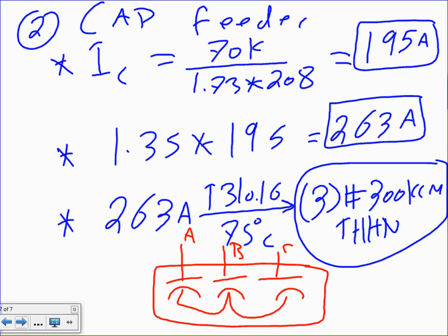And of course, you need a ground, right? Everybody knows there will be a grounding conductor going here, G. We size the grounding conductor based on the overcurrent device. You guys are good now, right? Equipment grounding conductor is sized based on the overcurrent device. That's how your caps are going to be sitting.